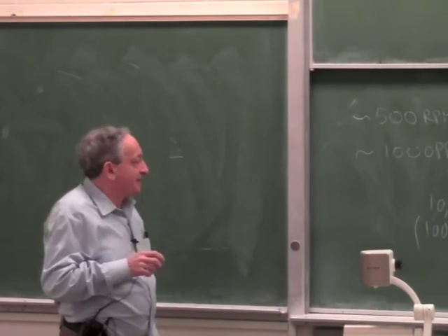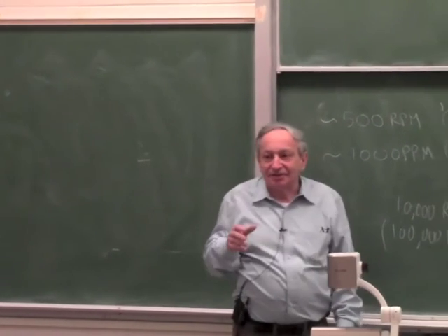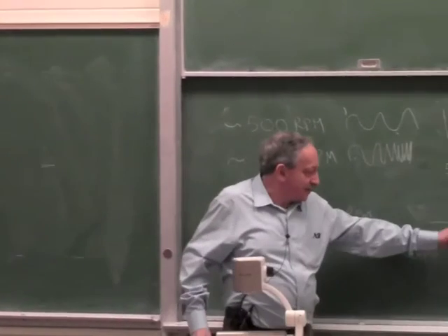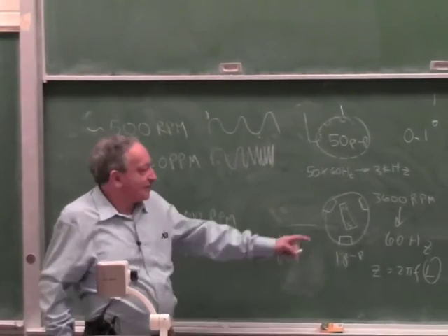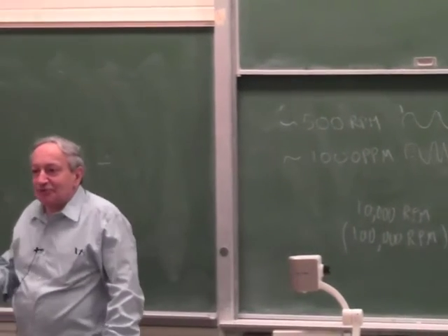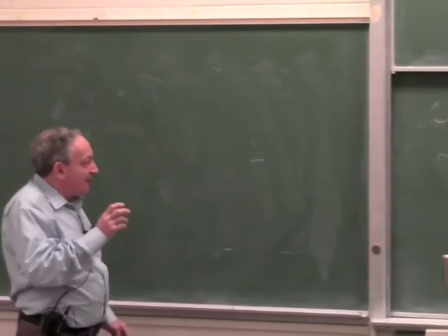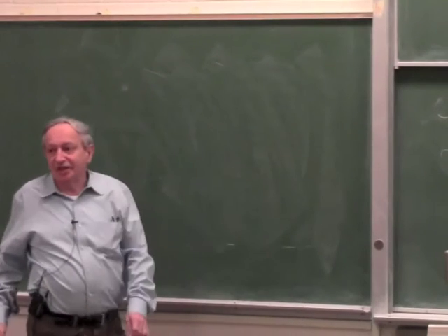Now, the fundamental reason why a motor like this, geared down, will actually have more power than the same motor in a stepper version has to do with some nasty detail in the magnetic field, which is called leakage field.